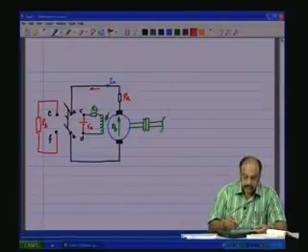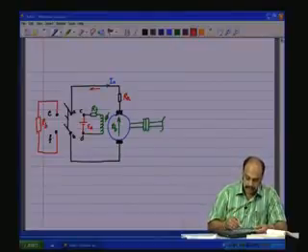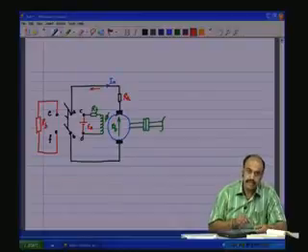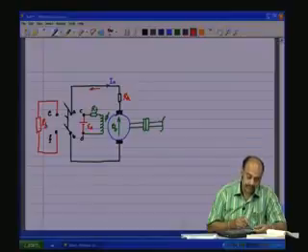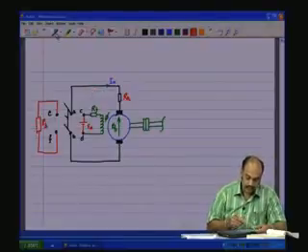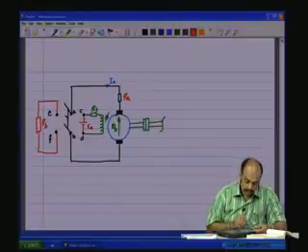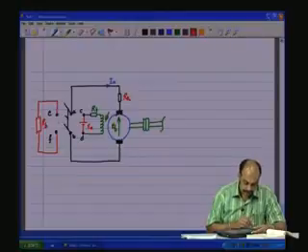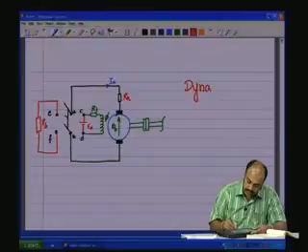So, therefore, the energy stored in the inertia, instead of being dissipated in the mechanical friction here, is going to be dissipated as electrical heat in the braking resistor RB shown here, due to the armature current now flowing through the resistor. This will bring down the speed pretty quickly, just like in a mechanical brake. Now, this kind of braking is called dynamic braking.